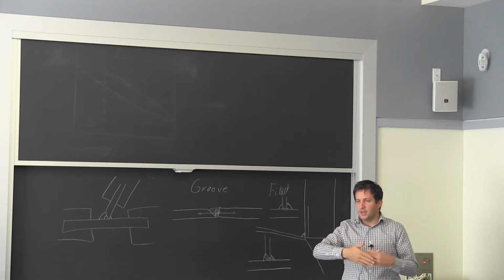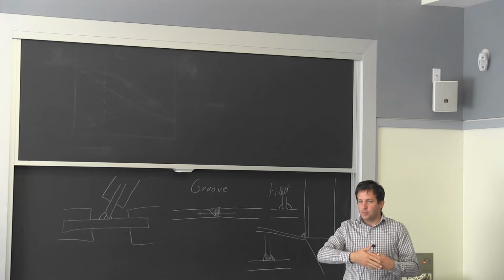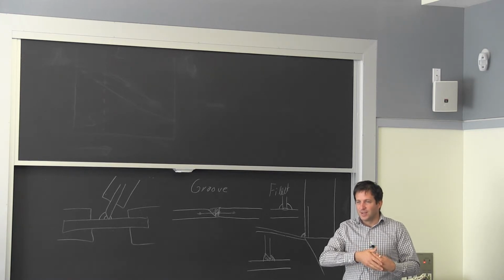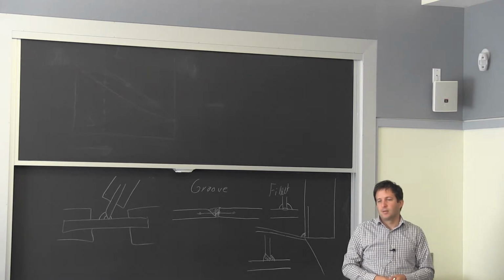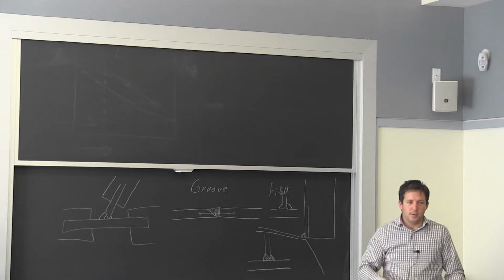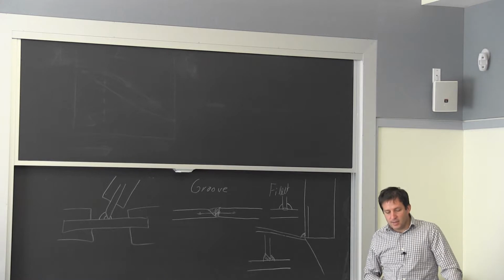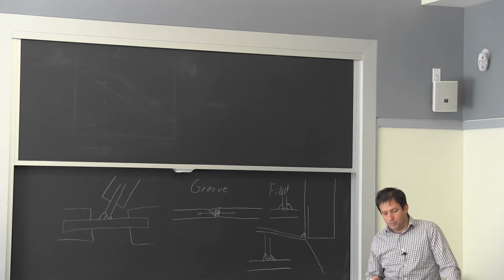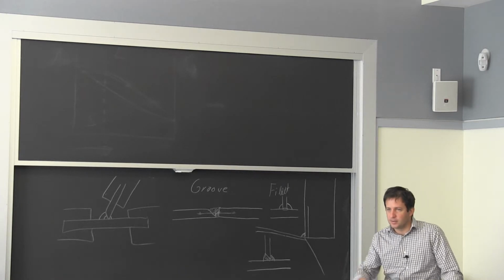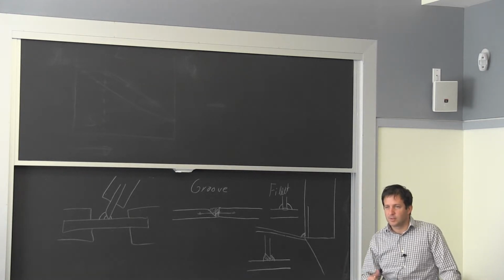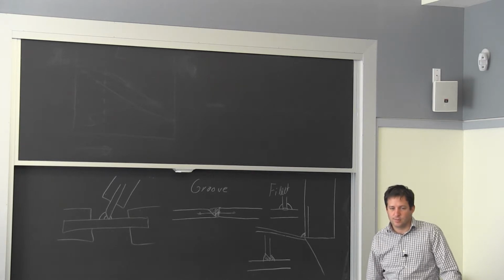But between that plate and the structure, they had to put bolts, but they didn't put the holes. So out in the field, you had to drill through an inch thick steel and then put the fasteners in. It's not terrible. There are drills that have a magnet and hold on to the structure, and therefore it becomes like a press drill. But it's still multiple operations as opposed to the welding expert just coming in, covering both sides, and let's go home.